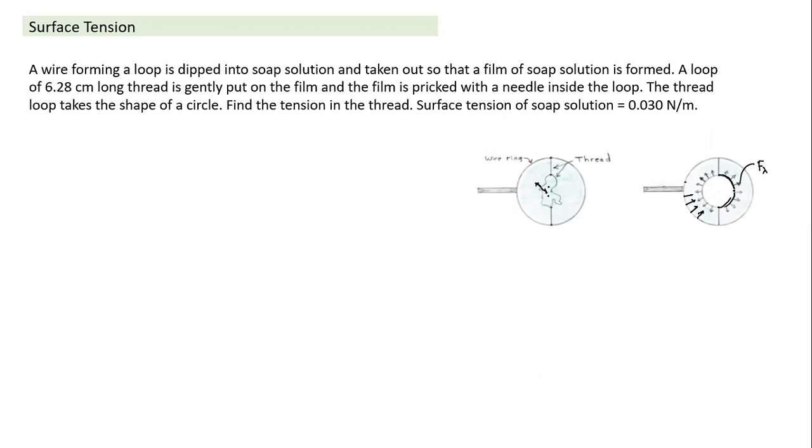If I consider the semicircular part, everywhere the force per unit length is constant, but it is acting in the radial direction. Since it acts in the radial direction, I cannot add up the magnitude. But if I take the summation of its component in x direction, it will be equal to the projection of the length in the y direction.